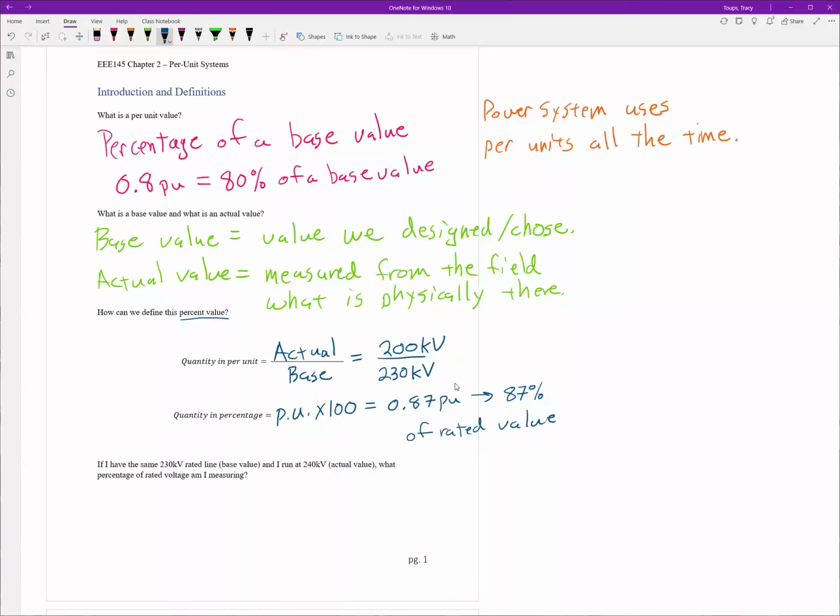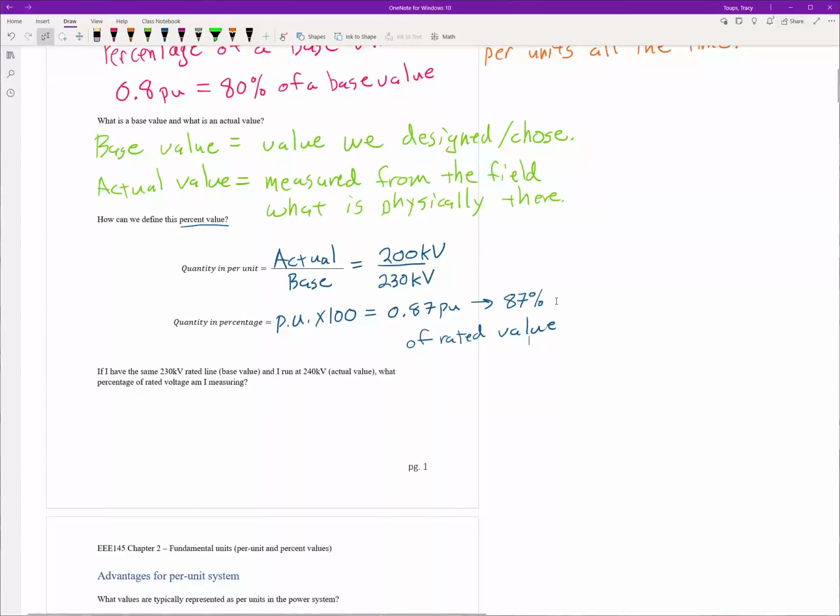Another way to say this is 200 kV is 87% of 230. So what I can see here is, hey, we're down 13%. That causes some alarm. Typically voltage, you don't want to see it go below 5%. Definitely under 10%, you're going to have some people starting to call. 87%, your system is still live, but we're probably going to have to fix it, right? This is a comparison. If this was like 20 or 30%, your system is already collapsed by then, okay? So in my opinion, or in most of the Power Engineering Society, percentage is much better than hard numbers.